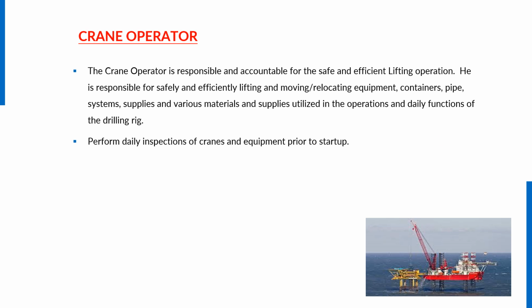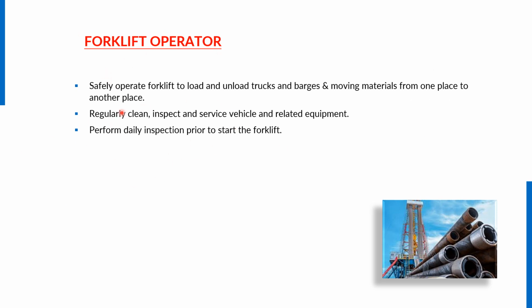The forklift operator is responsible for the transfer or movement of the load and unload. If that is an onshore rig, he unloads the trucks and trailers, and if that is offshore, there is a barge. In the barge, he's moving the material, and if there is an offshore company, they have a yard onshore. There the forklift is moving the materials from one place to another, and he also has to take care that the load should not exceed the SWL of that particular forklift, and do the daily operational checklist of the forklift.